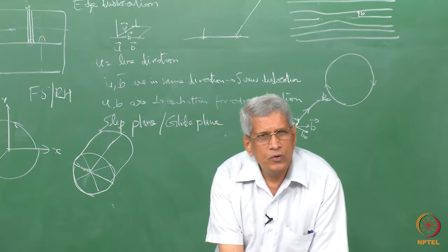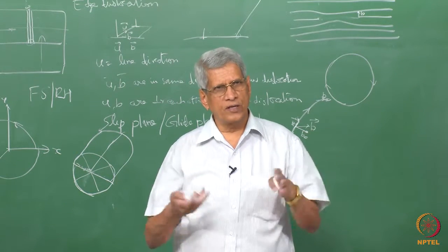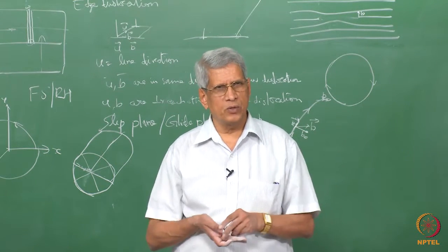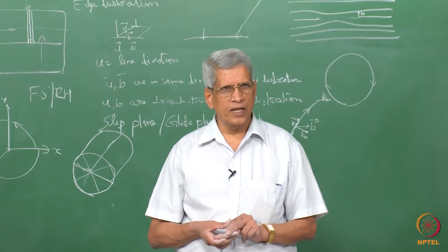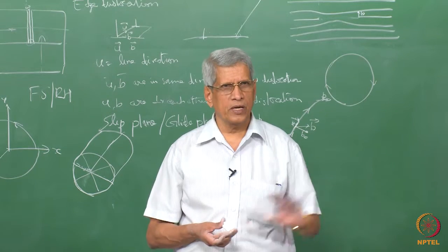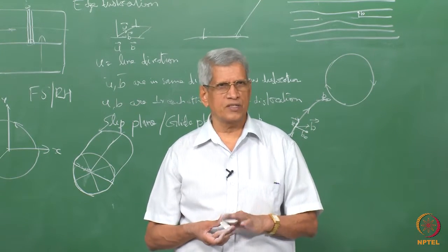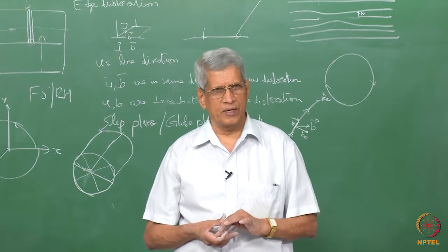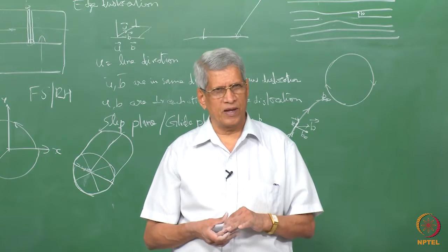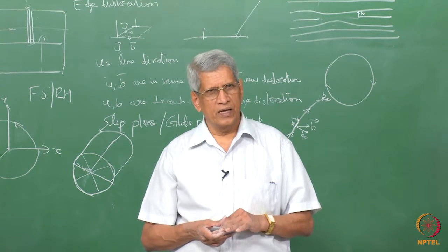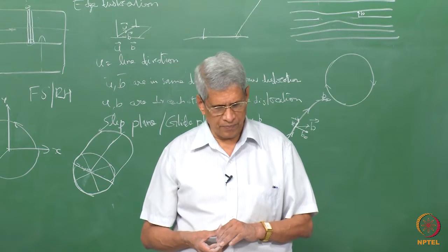So to get any information about the mixed dislocation, we can split it into a screw and an edge component, and that way we can do a calculation to find out the stress and strain fields associated with each, and then combine them together to get the total stress and strain field, to tackle the problem associated with a mixed dislocation.